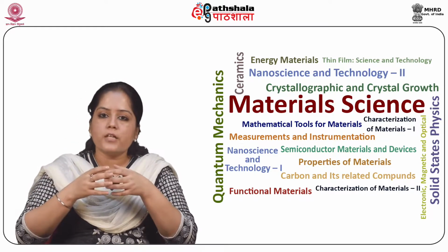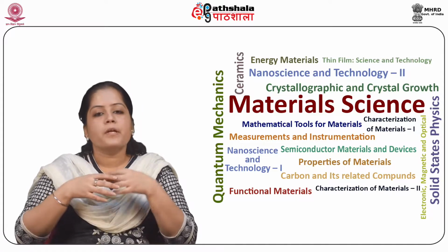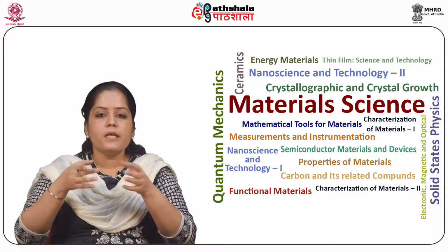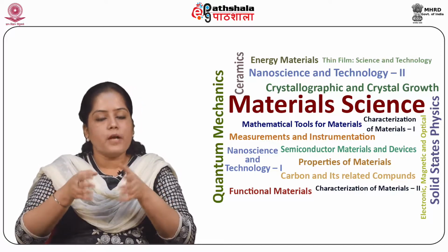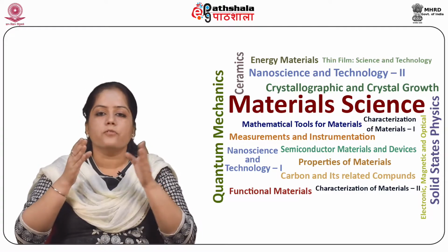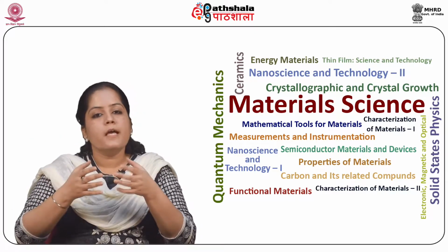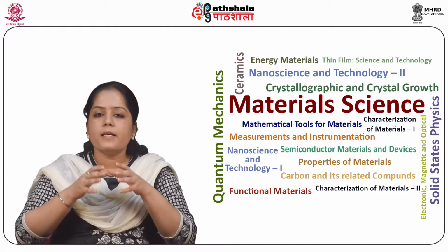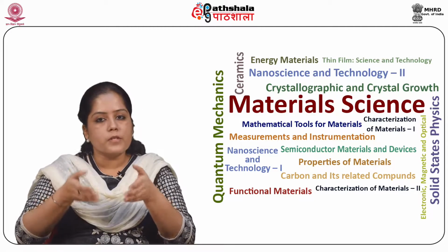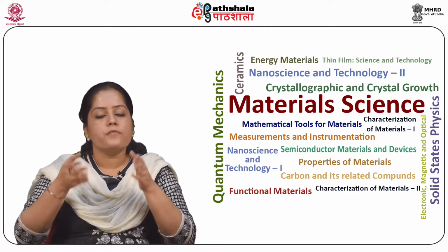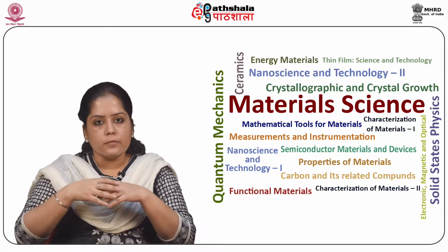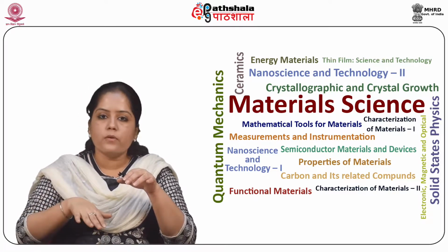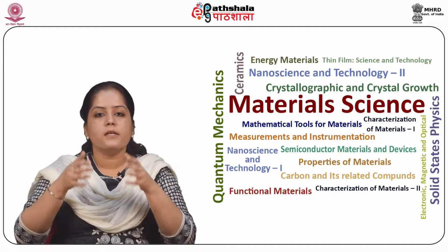Third, the theoretical fracture strength of brittle solids can be calculated and comes out to be of the order of E by 10, where E is the Young's modulus, and the actual fracture strength is lower by a factor of 10 or more. Next, the reason for this, as found by Griffith, is the presence of pre-existing flaws such as cracks in the brittle solids. So when a sample of such a material is loaded in tension, the most severe of these flaws propagates at a stress much lower than the theoretical strength and causes fracture.